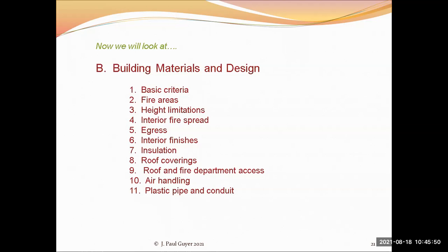And typically within the stairwell, there will be a standpipe, and that runs vertically the full height of the building. And at each floor of the building, there will be a tee-off that will connect typically to an automatic sprinkler system on each floor. And also there will be a connection point for firefighters to connect their hoses.